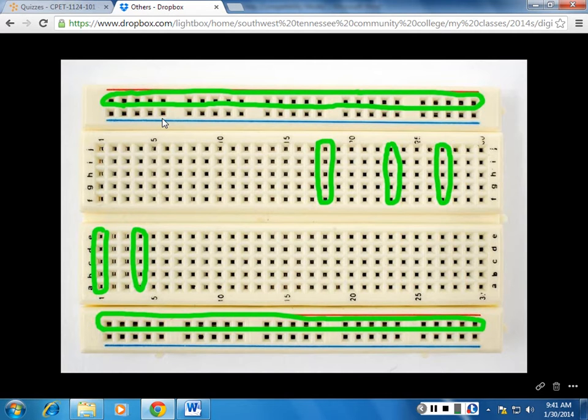It doesn't matter technically. But sometimes, do you see there are some lines drawn there? They try to draw a red line and blue line in most cases. They try to help you out a little bit, to tell you, okay, use the red one for VCC, blue one for grounding. Now, it doesn't matter basically, because it's just an indication. They probably try to keep you organized. When you have too many connections and too many voltages, you might want to use some of those, but it doesn't matter. Even if you use the blue line for voltage 5, technically that doesn't matter. But I hope that we will always be using the red one. Technically the circuit will still work, as long as this row is short.